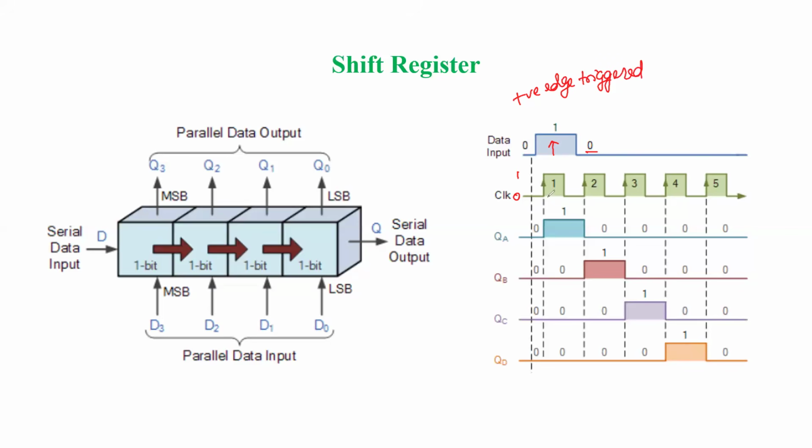So whenever a transition takes place from 0 to 1, like you are seeing in this case also, only then is the flip-flop going to trigger. Now for each triggering, since this clock pulse is applied to the leftmost flip-flop, after the first clock pulse flip-flop 1 has output 1. So that is on here.